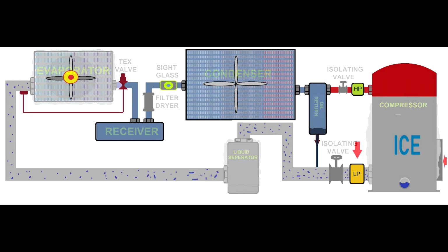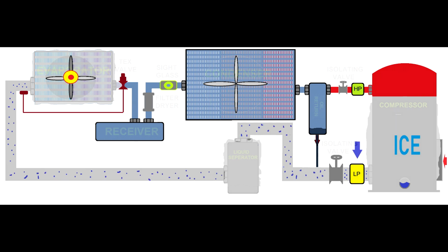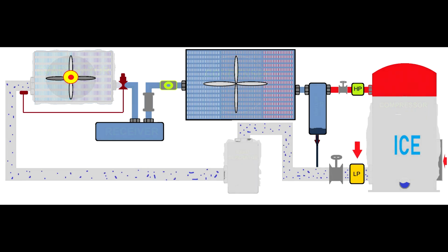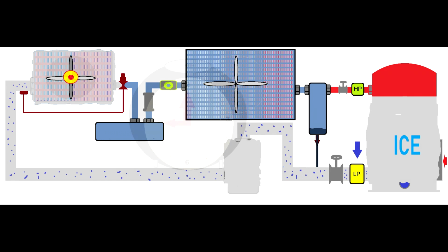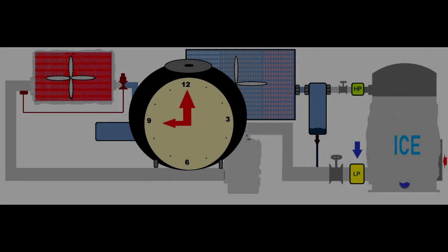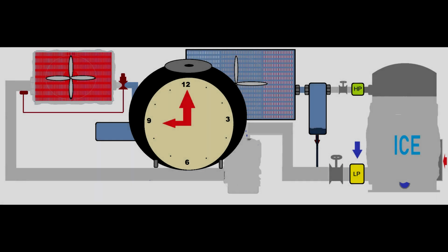If you have a dirty evaporator, or if the evaporator runs long hours in a humid environment at negative temperature, the evaporator ices up and the fan motor will get hot because you won't have enough air to suck. The low pressure switch might cut the system, but can you imagine, you cannot apply superheat anymore, and then your compressor will ice up.